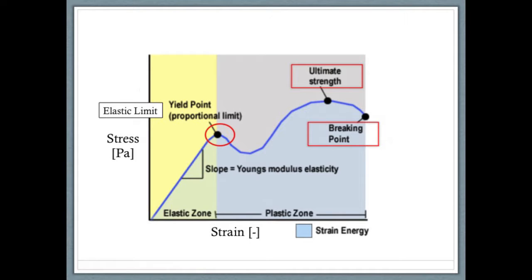So what about the last term, plastic deformation? As you can tell by looking at the graph, there is an elastic zone and a plastic zone. When a load is applied that remains in the elastic zone, like this line here, the process of loading and unloading follow the same path, resulting in an object that is the same after the load is removed. As you can see, this line here ends back in its original place, demonstrating a reversible change in length. This is known as elastic deformation.